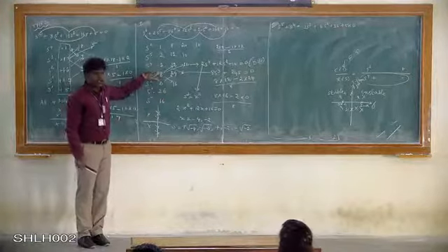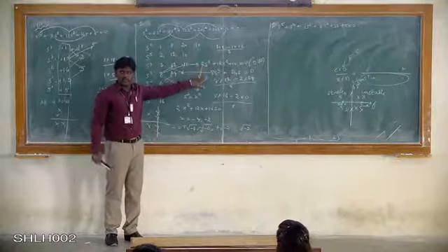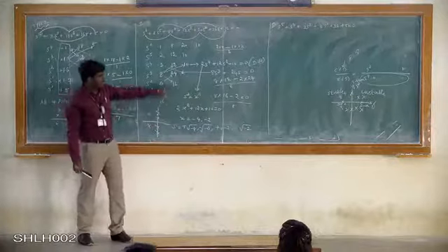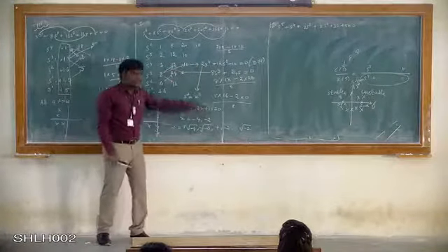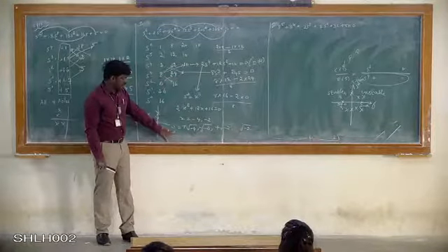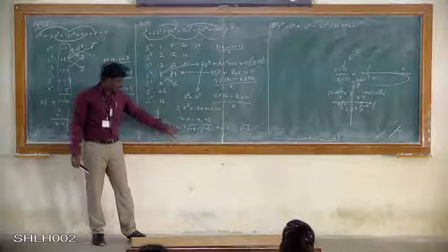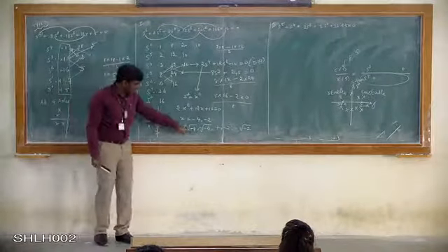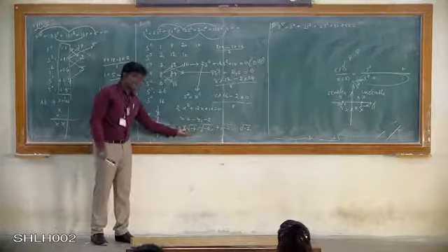Since one row became 0, we have taken out that particular equation, differentiated once, and we have finished our Routh table. Now you will have to take out that particular equation and find the roots for the same, right? So we have got s is equal to all these roots or poles. All these poles will be lying on the imaginary axis, because inside the root we have got -1, so it will become j.